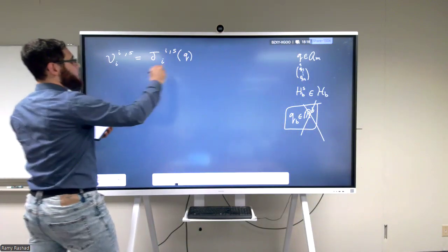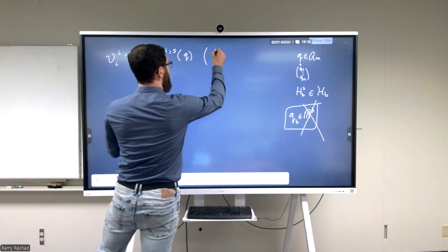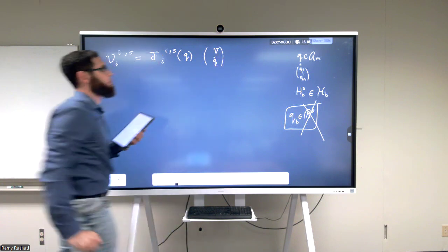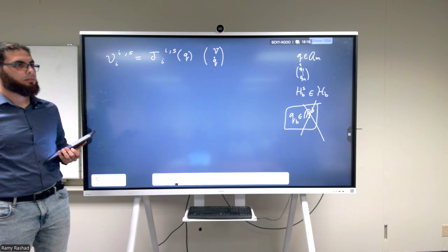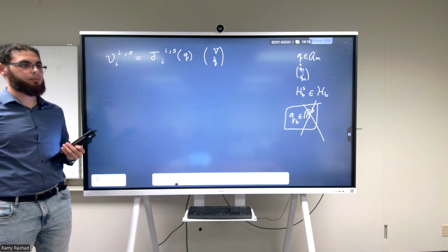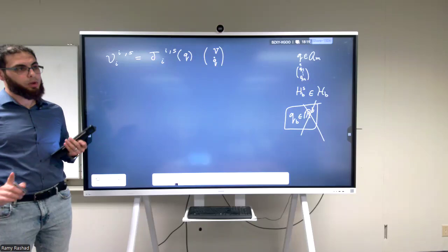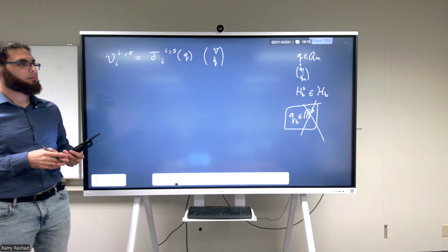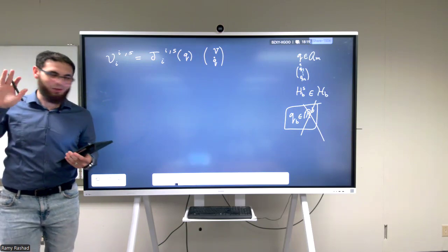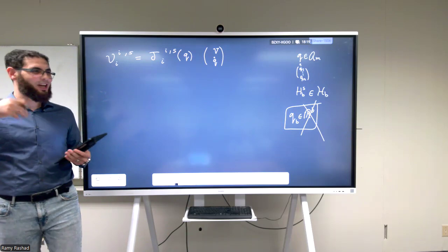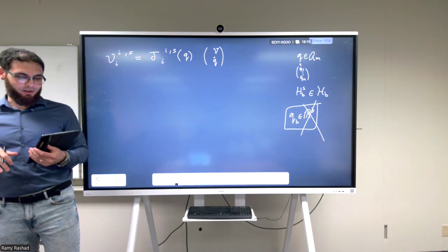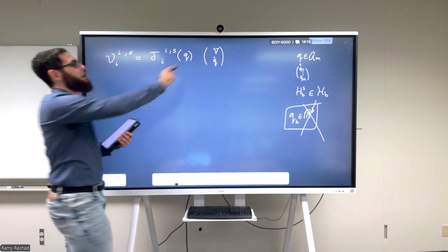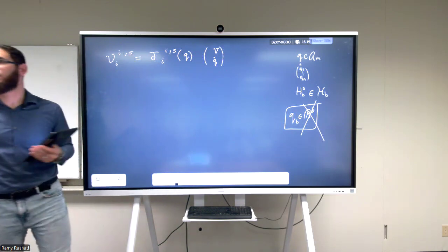So this is the key that we want to multiply this by a combination of the V and the Q dot. That's why you said it's not possible to parameterize it by six parameters, 6 values. Globally, yes, it's not possible. Locally, yes, you can do that. Locally, but not globally. If you don't understand, just keep it in the back of your mind, or write it down, and maybe hopefully in several years you can understand. So this is just what the Jacobian will do. It will map the V and the Q dot to the twist.